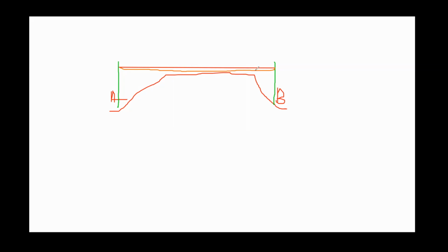So with sag here, since you didn't really follow the shortest distance, which is a straight line, your reading is going to be a little bit more than what it should be because you are following the curve, not the shortest distance. So that's for the sag.